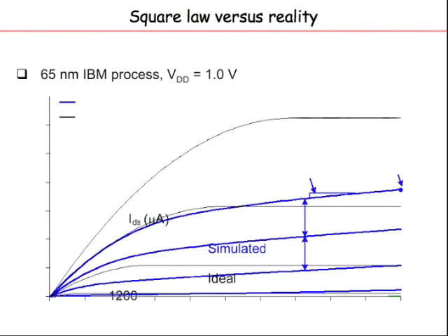Of course, in reality, this kind of model doesn't work anymore. So this is what the black curves are, the curves given by the model based on fitting to certain key parameters. But actual currents, you see three features. One is the currents are less. Second, I don't have this flat horizontal region, whereas the curves are going up. And thirdly, the spacing is growing. Why? If you take a particular VDS and look at the current as a function of gate source voltage, it's a quadratic.